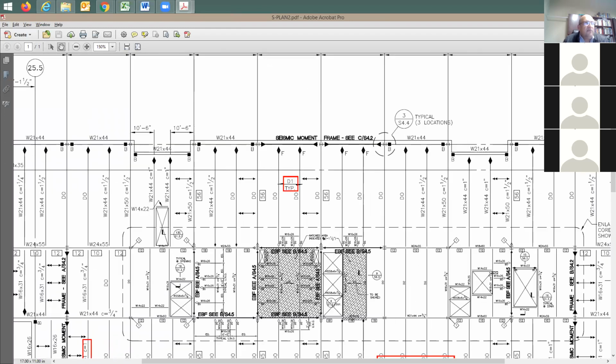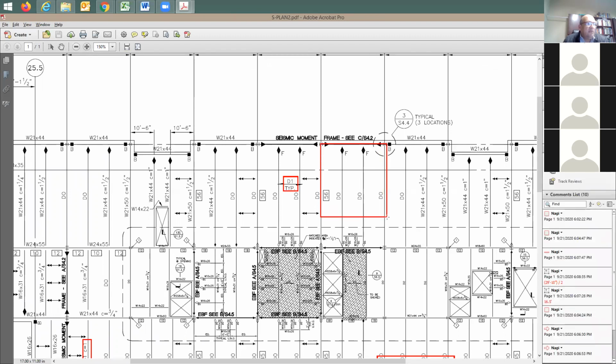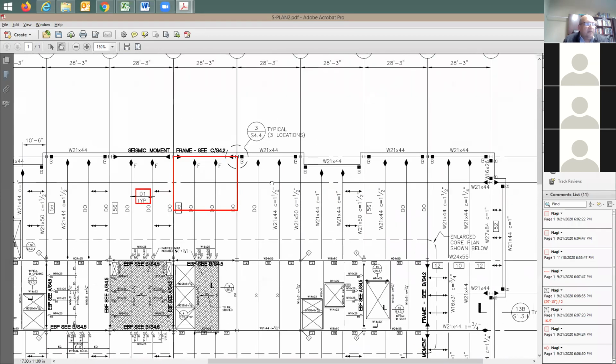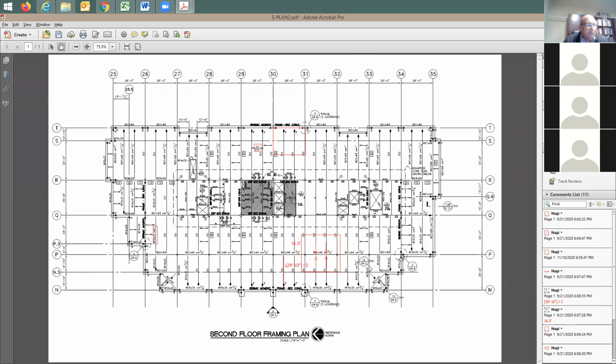So here's the size of the beam frame, right? So look at the amount of load that's gonna be coming. It's gonna be coming through this tributary width, right? So this tributary area is very small. It's not really big. So you don't really need to reduce it, but if you wanna reduce it, go ahead. Okay. So in submittal, we don't need to reduce it. No, you don't have to.